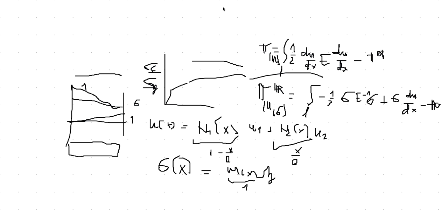So you can try to do this, what I was giving you to go to fracture, with, for example, the bar load equal to 1.5 times sigma f, to be at least 50% larger than the fracture stress. You choose the coupled damage plasticity, and you check what happens, and how much more easily you can get it when you have a stress type of interpolation, just to demystify what I'm telling you in this particular case, okay?